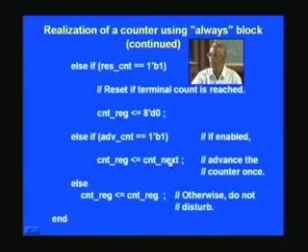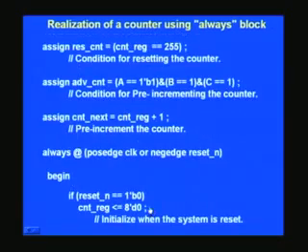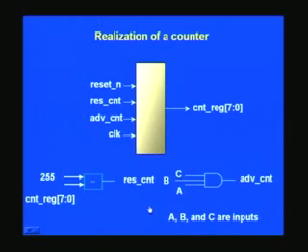And here we could have put the same counter reg plus 1 right here. That also will work. But what is happening, only when the clock strikes, it starts computing. Right? So with this, if this is not satisfied, we'll not disturb the contents of the counter register. So are we clear about the whole thing?